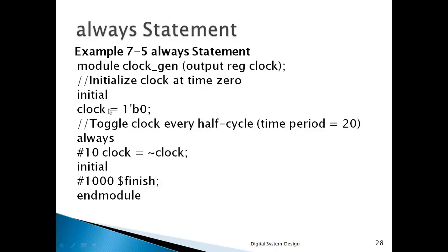Here the initialization of clock is in a separate block. This should not be used inside the always block because the block repeats again and again, and this initialization would also be repeated if it is used in the always block.